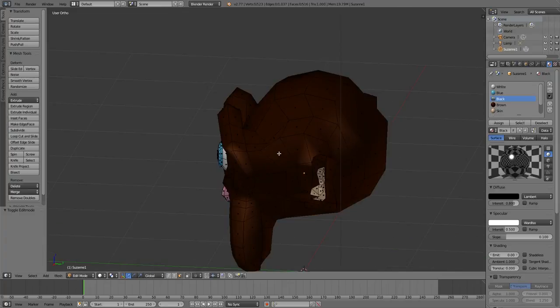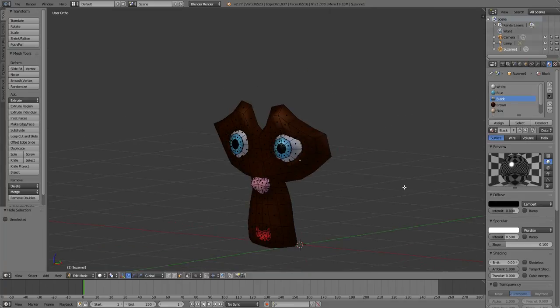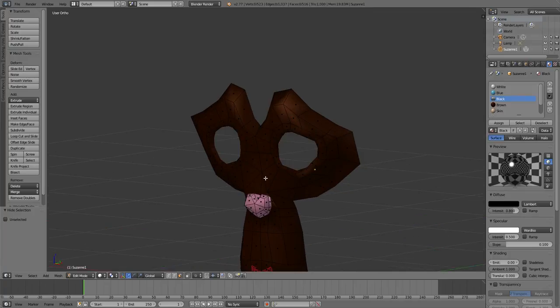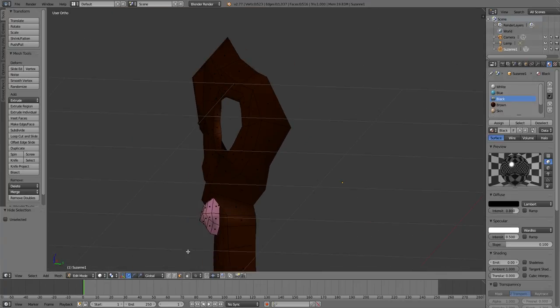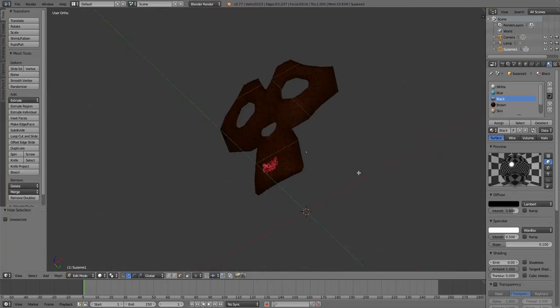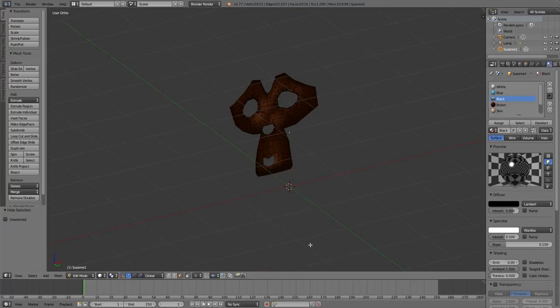So we're gonna single out the face. Select, not that edge loop, but maybe this edge loop, and go H. Click L on her head and click H. Go L there, H. I'm going to deselect the nose. So select this edge loop by Alt, Shift, right click, H, L, right click, H, L, and we're going to deselect the mouth, Alt, Shift, right click, H, L, H. Okay, now we've got a face.